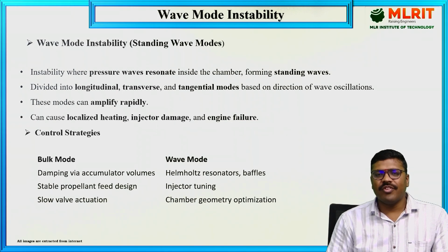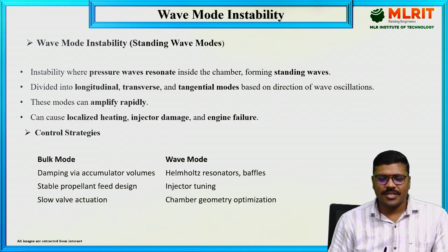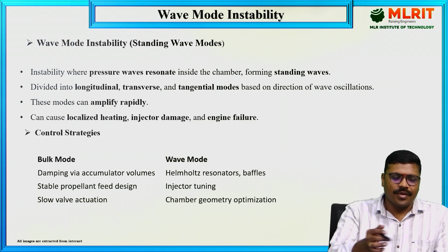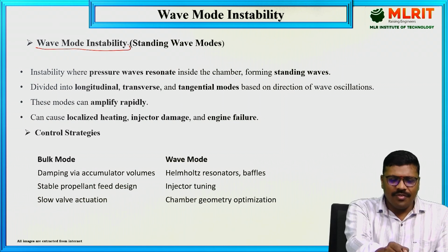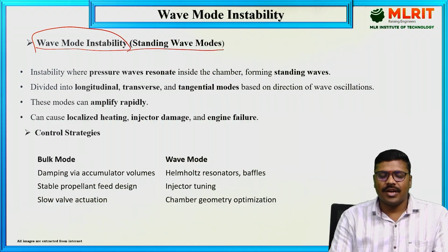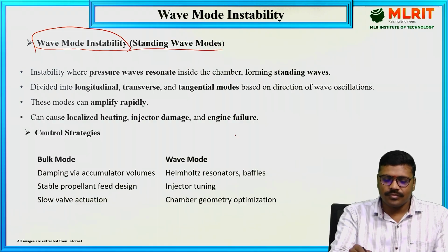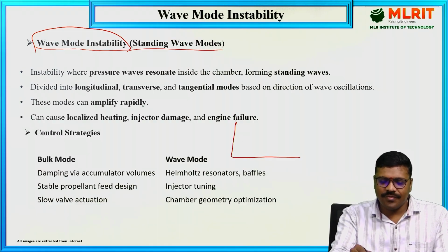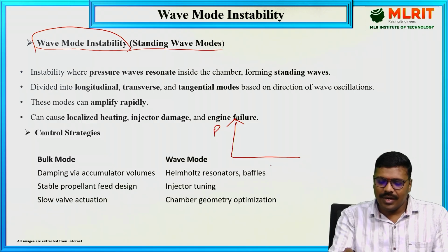So next is the wave mode of combustion instability. The wave mode of combustion instability is also called standing wave modes. If you consider the pressure along the combustion chamber length, then the pressure fluctuates like a wave.